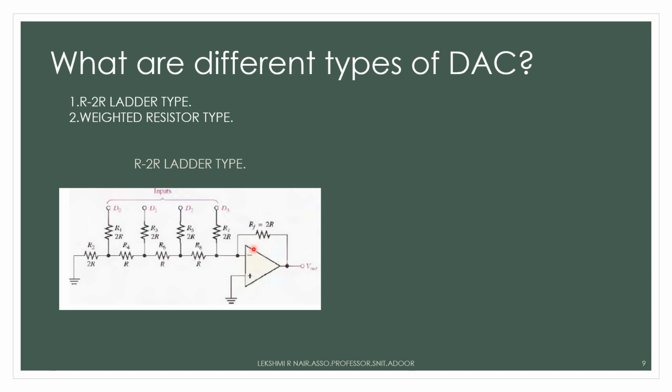The main component is an op-amp. The op-amp has a feedback and an input. Here we can see that input is given to the inverting terminal and the non-inverting terminal is grounded. So we can say that the op-amp is connected in inverting mode.